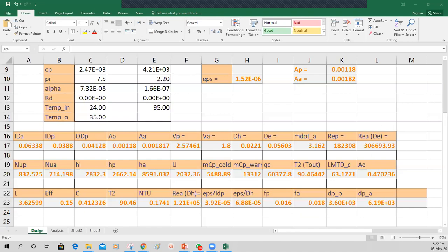For safety reasons, you can decide the boiler temperature rise, let's say it can go up to a 50-degree rise, not more than that, or a 40-degree rise, not more than that. So I can choose delta T, let's say that at any instant the boiler can raise up to 40 degrees. Cp I know for water, and the capacity of the boiler, let's say it is 25 liter. So I can change it into mass. So now my unit is energy, right?